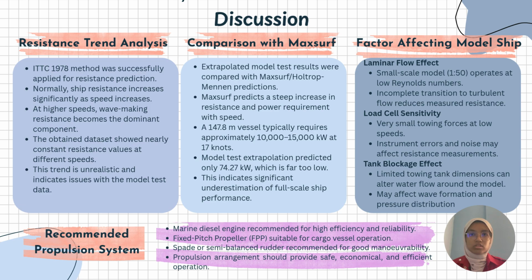However, in our result, the resistance values remain almost constant at different speeds. This is not what we normally expect, and it suggests that there may be some issues with the model test data. Next, when I compare the extrapolated result with the MaxSurf prediction, I found a very large difference.